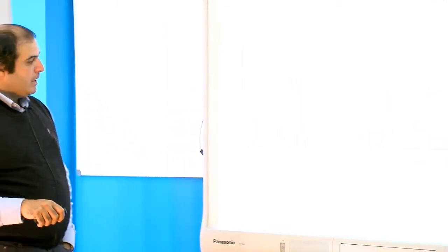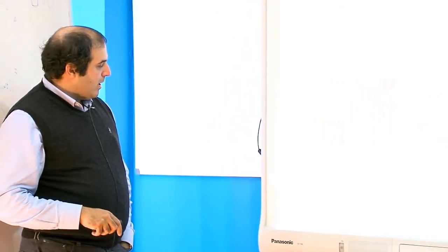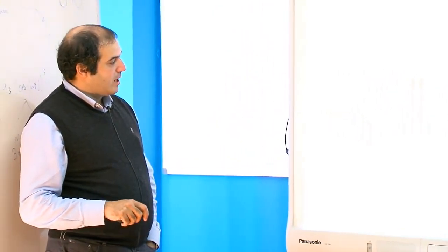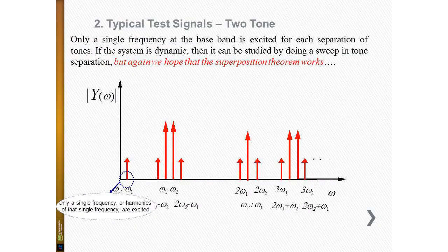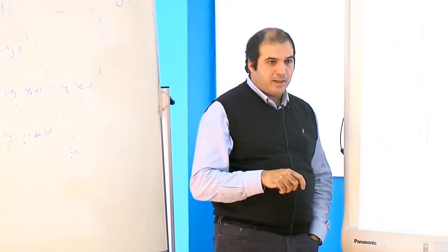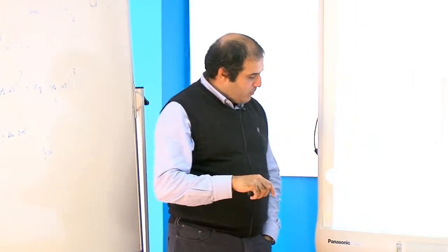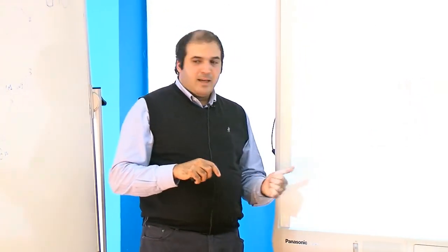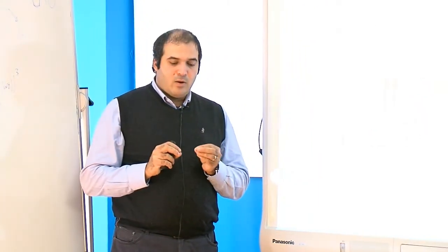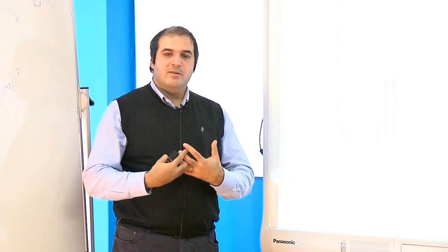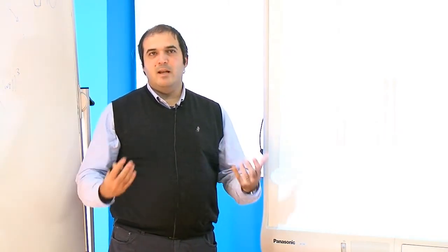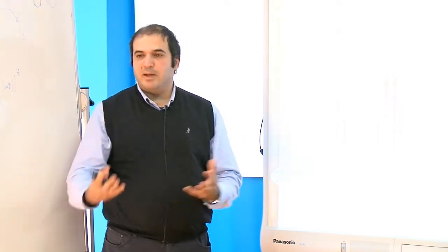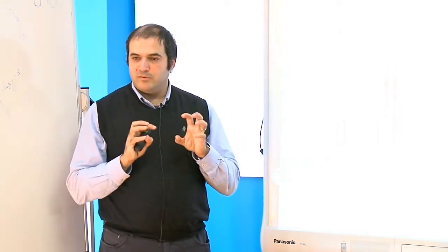So this is the output, and what we see is that, okay, I already have inside information, I didn't have that with one tone, and now I have this video bandwidth here, you see. The problem I mention here is that, as I said, when I want to extract a model, I want to excite the most, or the biggest number of state spaces of my system, because I want to capture all the information.